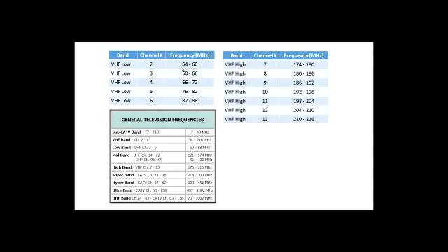Then another channel is also going to carry over 6 megahertz, with the same proportional frequencies when it comes to employing the bandwidth assigned for that channel. So if you look at this here, every channel has 6 megahertz of bandwidth: 66, 72, and so on. The difference between the higher and the lower is going to be 6 megahertz. So that's how the cable TV channels work.